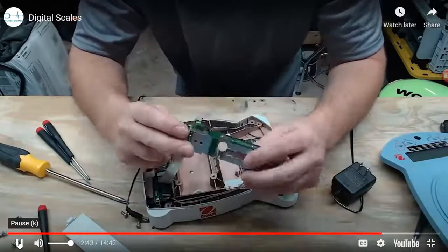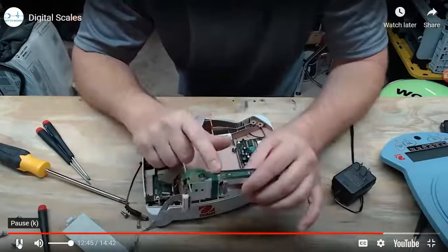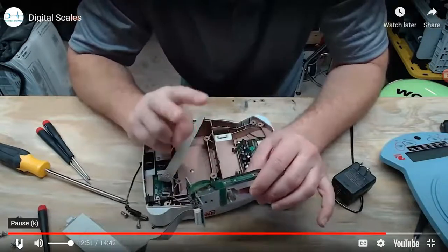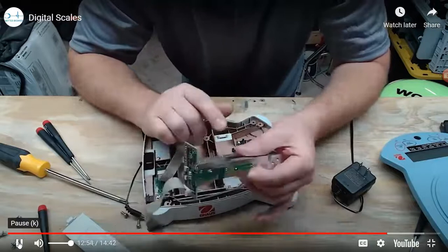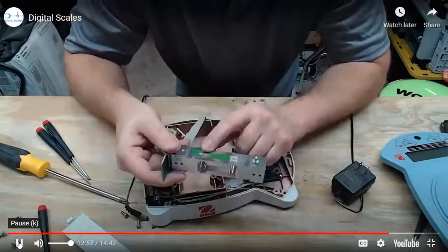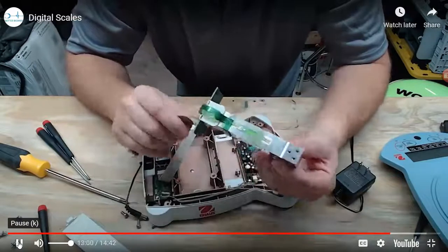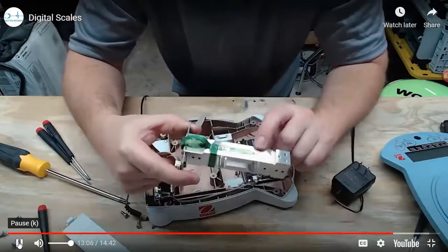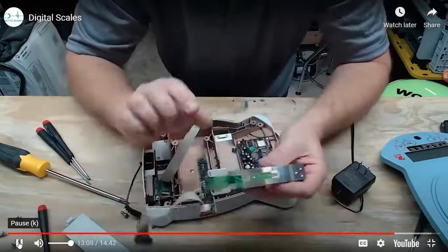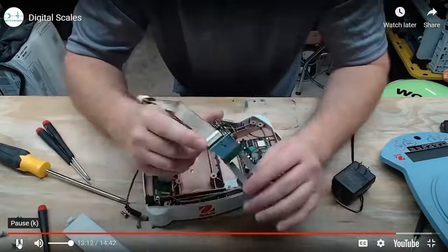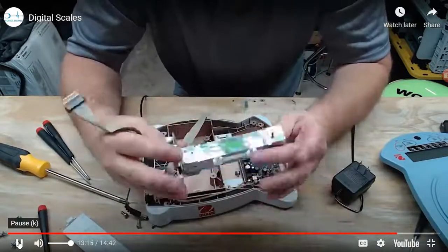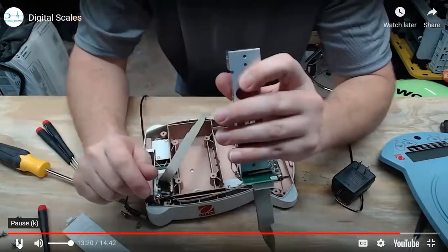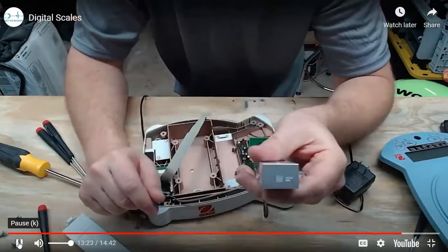This is actually very interesting. So you can technically measure these with ohms to see if they are close in tolerance. If you have one of these little strain gauges that's got a much larger ohms value than the others, then that's going to be your problem. This is going to be a throwaway part, of course, unless you really want to figure out what that strain gauge is. But getting a matched set with the same ohm value is going to be very difficult. So this entire component would be exchanged. Take a look at that. There's a serial number and a part number right there on the end cap.